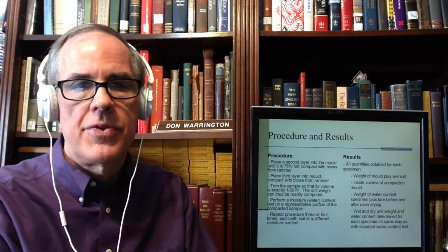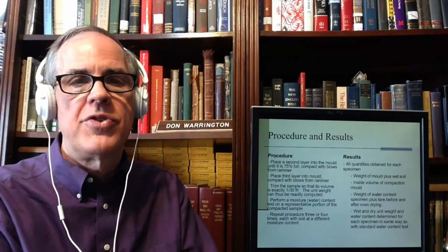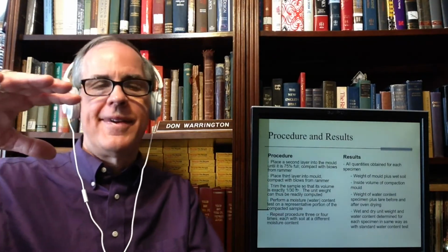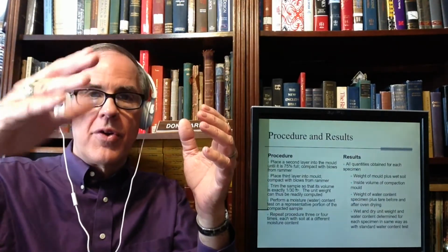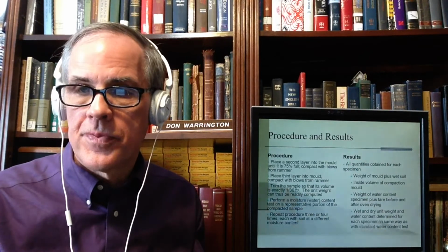And then once you're done, you'll take the top ring off, and there'll be a little soil over the top, so you trim the specimen off,